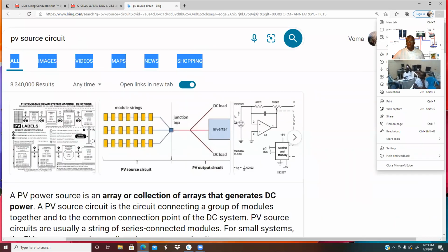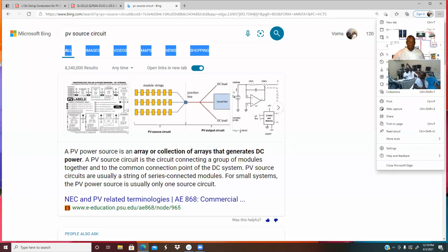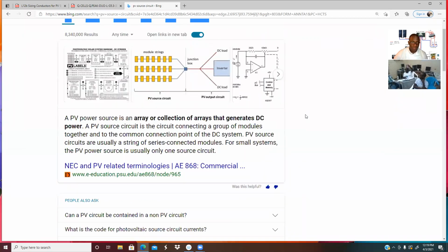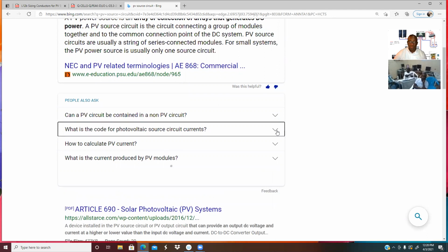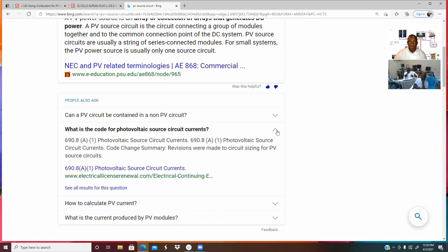When the temperature rises or the condition becomes harsh and the current increases, you pass through the wire. If the wire size is not big enough, the damage can cause overheating or fire. But when the wire size is big enough, even when the current rises, the wire will continue to let that current go through. So that's why we add the additional 1.5 to the maximum that we first discovered in the first part of the calculation, so we get a system set for protection.